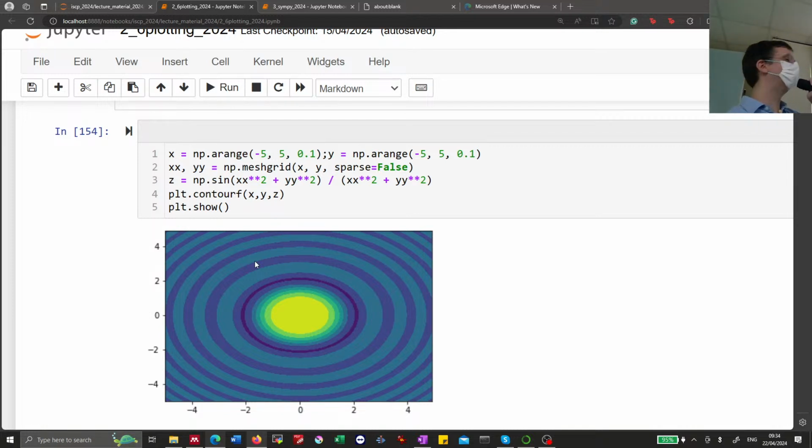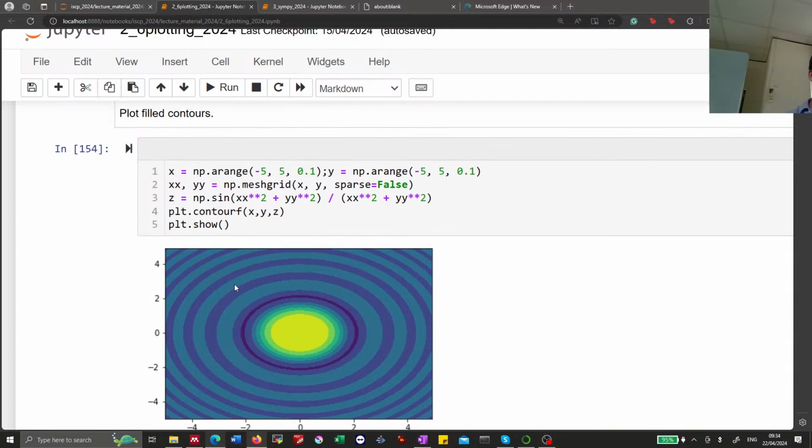So how does the contour map work? Well, the contour map gives you values at intersections between different contours, and then intervals where these contours are valid. For example, from 30 to 40 meter. And then you have a new contour from 40 to 50 meter. So why would you do that? It simplifies plots. Right? It makes them maybe easier to estimate where certain values are. Right? How steep is your mountain?